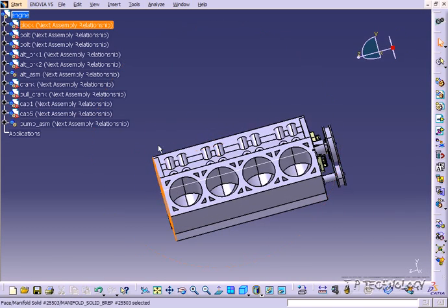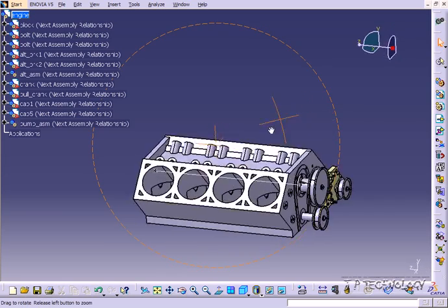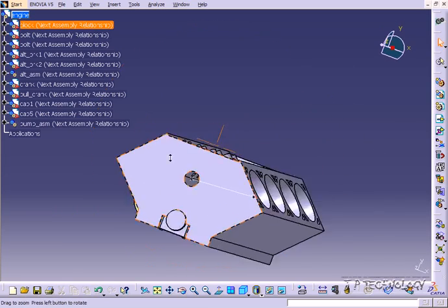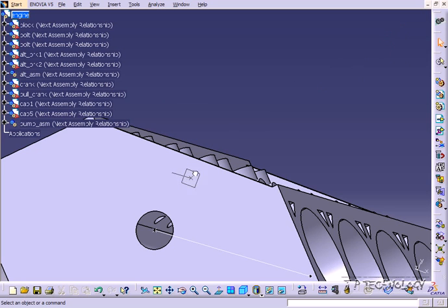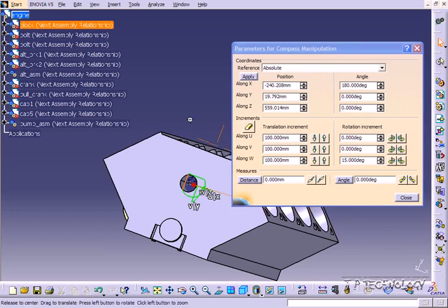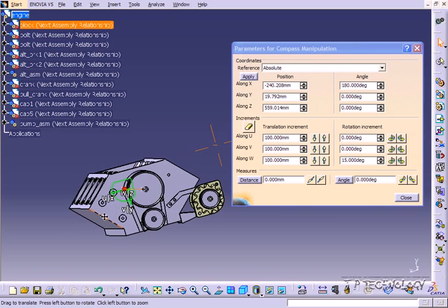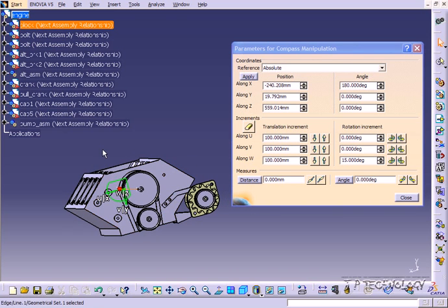Now we have our axis line, so let's throw our compass on it. Zoom into it and throw the compass and make sure that it's right on it. You'll know when it's on it when it snaps to that line. And let's double click and go into the properties. So now again, you're able to go through the assembly and use the hierarchy system and pick which parts and assemblies you want to move.